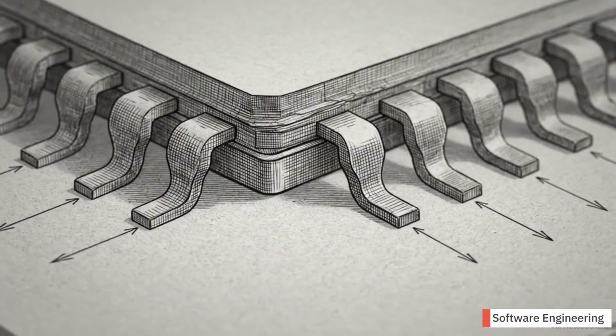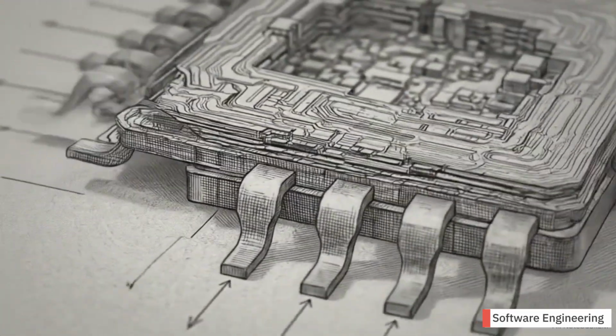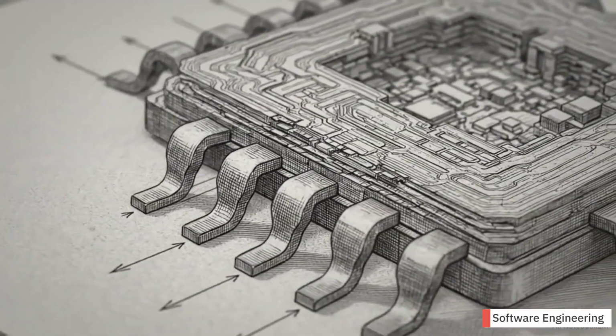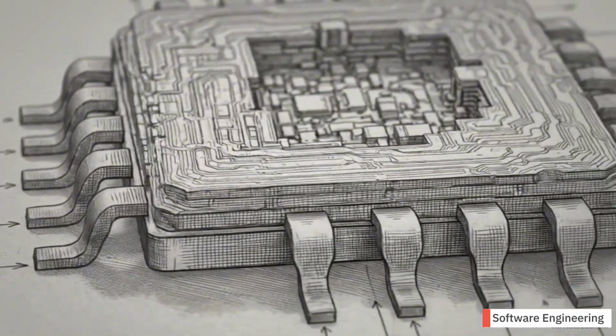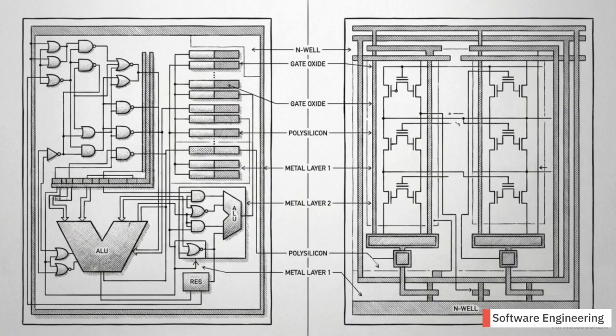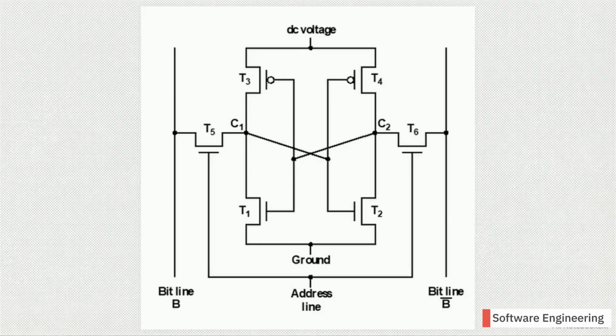To understand those physical compromises, we look first at the actual physical construction of static RAM, or SRAM, the hardware used for CPU cache. SRAM is constructed using the exact same process technology as the CPU logic itself. This schematic shows the defining physical characteristic of SRAM, the 6-transistor, or 6T, memory cell design.